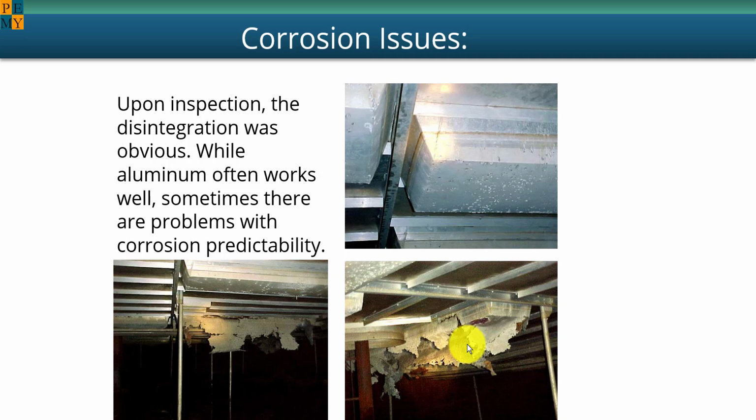The problem with aluminum as a material is that it's a little bit unpredictable in liquid service. So the aluminum frying pan that you use, or maybe you don't, most people have gotten away from that, but the oxide layer, because aluminum is exposed to air, is very good at inhibiting corrosion. But when you put it in a liquid surface, the oxide layer can easily be destroyed, and so it's quirky in terms of corrosion and has to be carefully selected by an experienced metallurgist if you're considering aluminum.